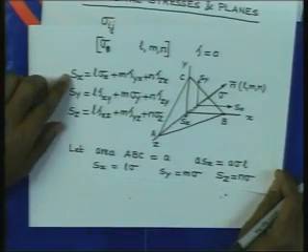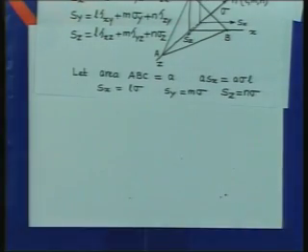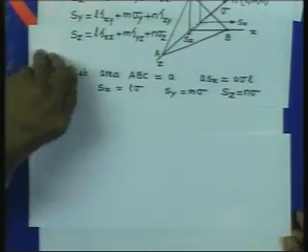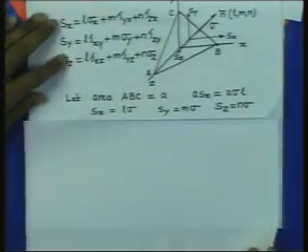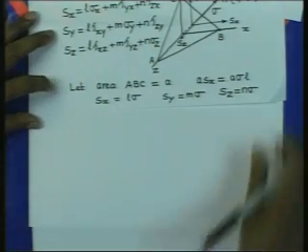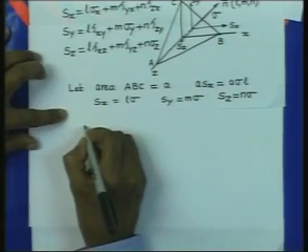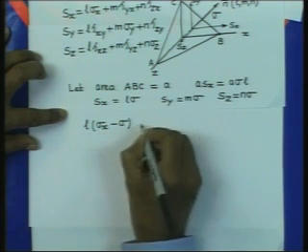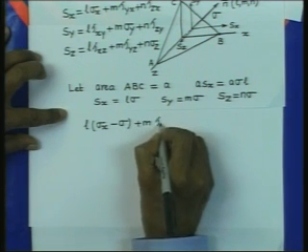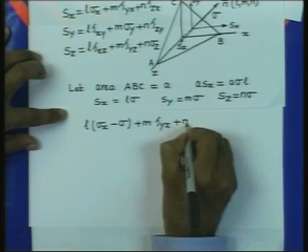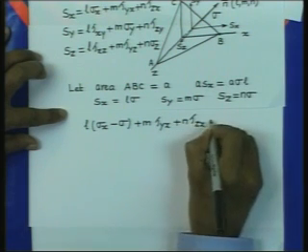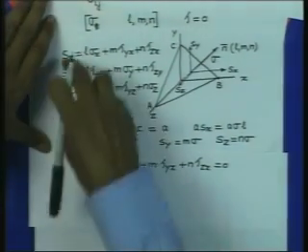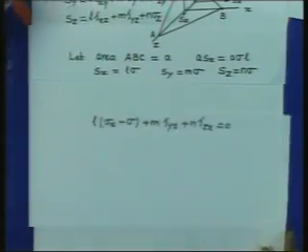Now, we will substitute the value of Sx, Sy, Sz in terms of sigma. If I do that, we finally get the following: L sigma x minus sigma plus M tau yx plus N tau zx equal to 0. So, what I have done is that I have coupled these relationships for Sx and simplified.